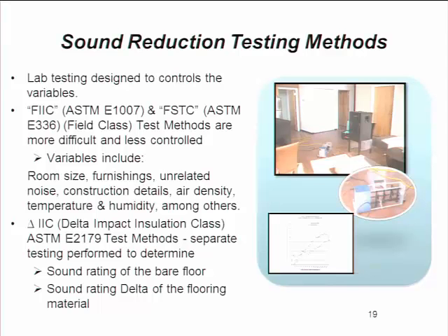Looking at the IIC, this is the one number that, if you're only going to look at one number, would be the number that I would recommend, because it gives you the correlation associated with that particular membrane and that particular system. And it's an easier comparison than going through all of the other detail if you're only looking at one number.